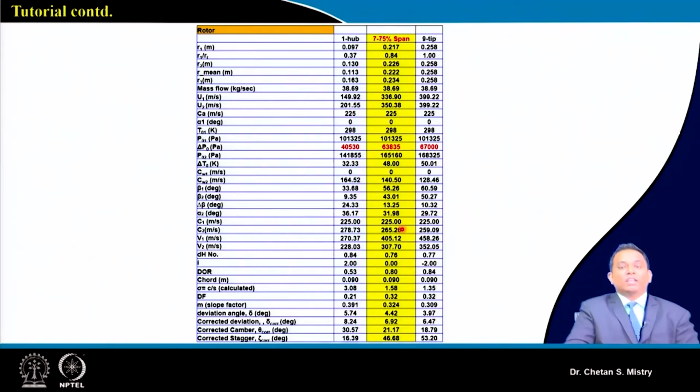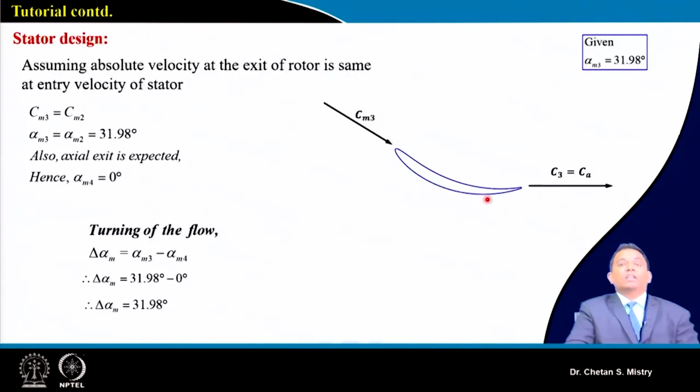Here in this case, these numbers are coming to be in a slightly lower range, in the subsonic or high subsonic range, so we can safely go with a subsonic kind of stator. That's the reason why, if you look at this aerofoil, it is a subsonic aerofoil. We can go with a C4 kind of aerofoil for this. Initially you can go with the C4 aerofoil, later on as per your requirement you can modify the shape, you can morph your aerofoil as per the expectation.